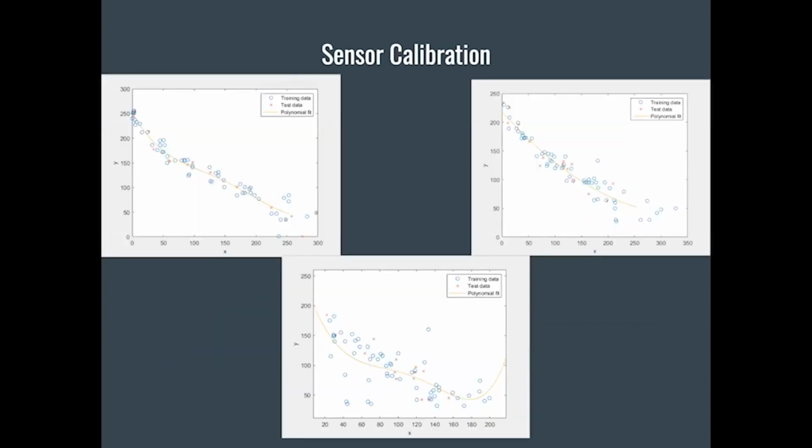Here you can see the graphs we generated by using MATLAB's curve fitting toolbox. In the top left-hand corner is the R value, and you can see the function maps pretty closely between the sensor value and the correct R value. In the other top slide, you will see the green value, and at the bottom, you'll see the blue value. As you can see, in the beginning, we had a lot of extraneous data with the blue sensor. However, once we implemented our nesting design, we were able to get rid of some of those extraneous data points and get a much more accurate curve fit.